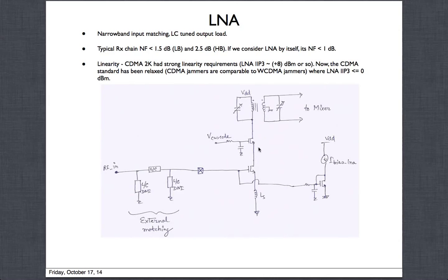That is not shown in this picture, but just to give you an idea and a hint, we have to find different ways to change the gain of this LNA. When the signal is low, it should provide the maximum GM or maximum gain. When the signal gets stronger, you have to lower the GM, lower the gain, so that this guy can actually handle it.